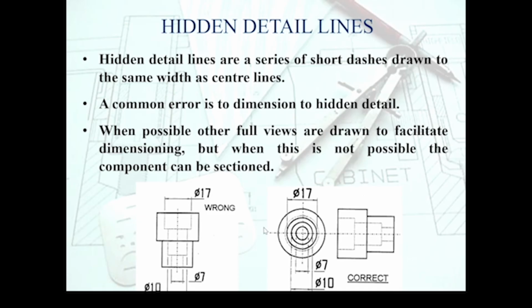What is allowed though is to tilt that object sideways and probably refer to some other views, and when that becomes a visible edge like this in this particular scenario, this is an acceptable practice. So sometimes you can pick an appropriate view to communicate all the details on the inside, and this is actually quite a nice example because all the circles go in one direction only, so you are able to see all the diameters and all the heights in either this view or in this view, and that complements each other, and this is probably the better practice.